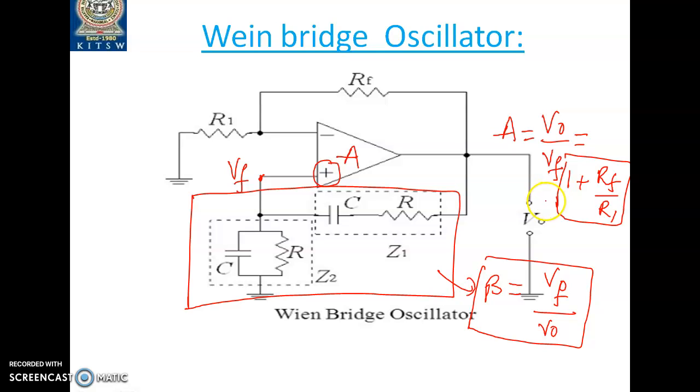So therefore we have applied the feedback arrangement to the non-inverting amplifier. Now let us see whether it is producing a phase angle around the loop equal to 0 or 360 degrees. As the name itself indicates, this is a non-inverting operational amplifier. Non-inverting means the output waveform is in phase with the input waveform. So obviously the phase angle around the loop is 0 degrees or 360 degrees.